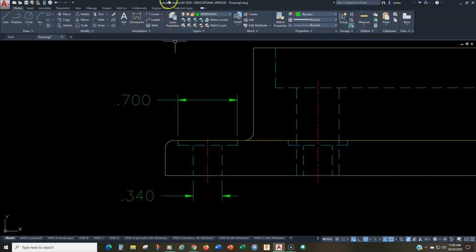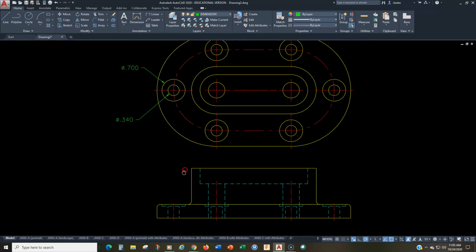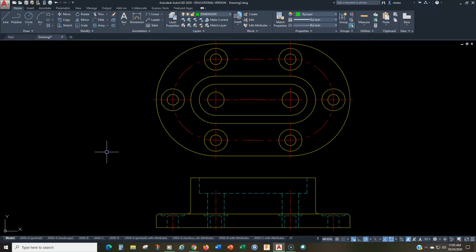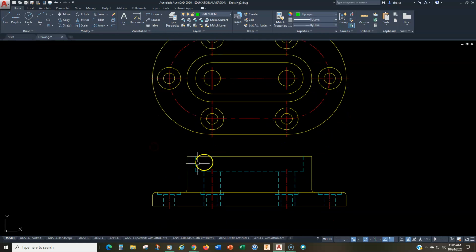So what is typical, what is standard when you're drawing this is to draw it with a depth of 0.06 inches, okay, or 2 millimeters. All right, so that's what I drew this as. And that's what you should draw this as, okay? So let's go on. All right, so that's taking care of the dimension for those 6 holes, actually. Everything else should be pretty straightforward.